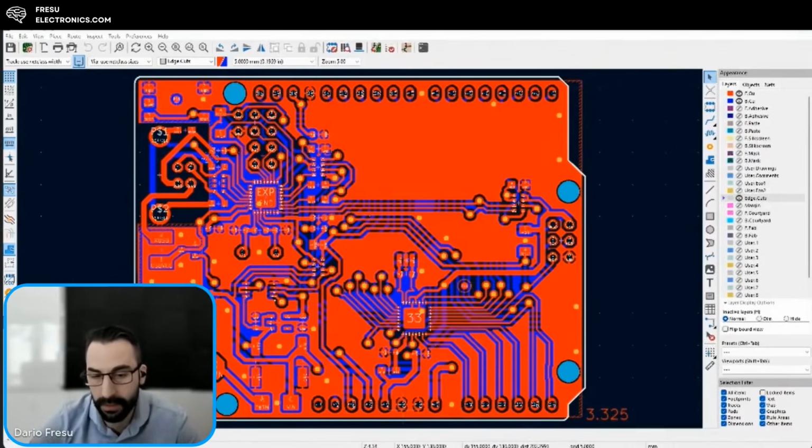So the software that we're going to use is Simbeor, and we can see the board from the signal integrity perspective. Why the signal integrity perspective? Because this is the most important one as it relates to electromagnetic compatibility results. What the software does is essentially analyze the board in terms of signal integrity, and already this is going to tell us three important things: the return and reference plane, the impedance discontinuity, and the crosstalk. So three different things, which are the most important things.